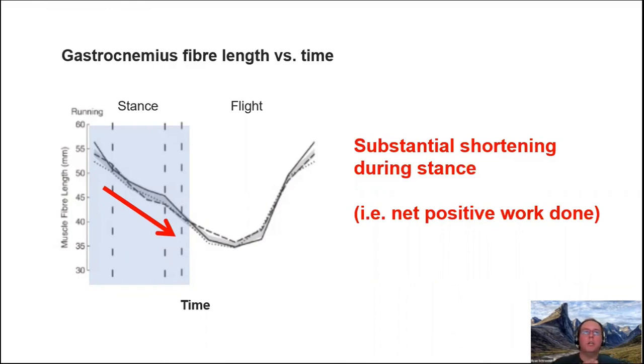Or if you have a stiffer spring, and by the way, the spring is, of course, not a single tendon in my model. It's sort of a composite of all the compliance and elasticity within the whole leg, right? But regardless, if you have a stiffer effective leg spring, how does that affect the physics, right? So, okay, you have a spikier ground reaction force. You fly through the air for longer and these sorts of things. So although these might not seem like mechanisms to someone who thinks about individual muscle fibers and cross bridges and things like that, I would argue that they are perhaps mechanisms of a different scale.